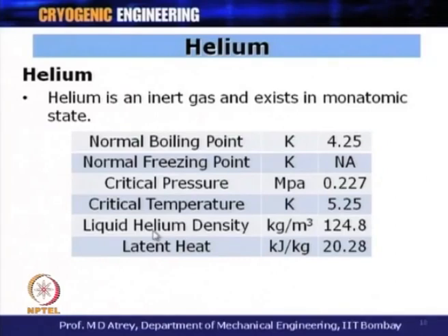It means that with the smallest heat coming in, the liquid helium will get evaporated, and so one has to be very careful in the usage of helium. Heat leaks happen when you use liquid helium. It is a very important parameter, because the latent heat is what gives you the amount of cooling effect, or refrigeration effect, that you want at 4.2 Kelvin.